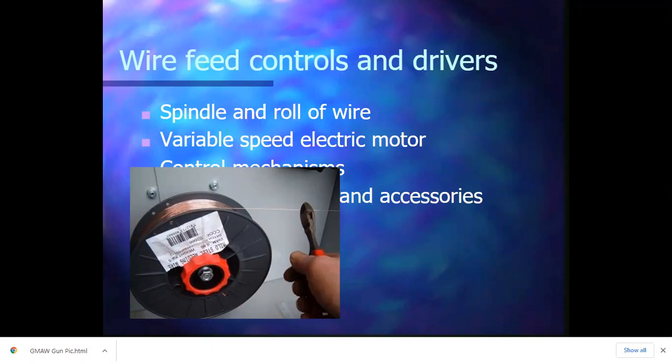But if you don't secure the left side there, what's going to happen is you're going to cut it, it's going to spin around, flip around, unroll a whole bunch, and you're going to waste 50, 100 feet of wire, potentially even the whole roll. So always secure that side before you cut the wire. The right side doesn't matter. It's secured by the drive rolls. It's not going anywhere. The left side, you've got to hold that.